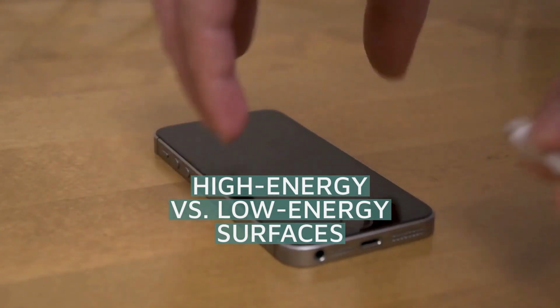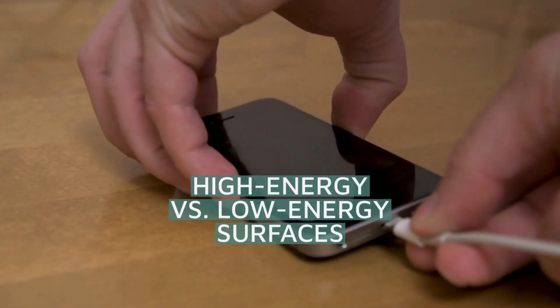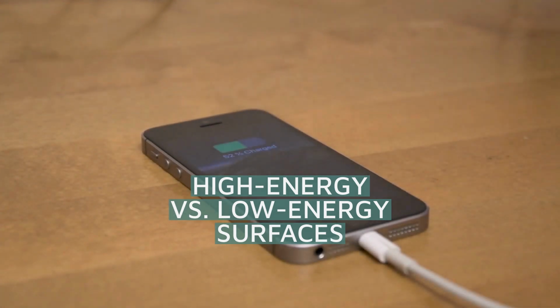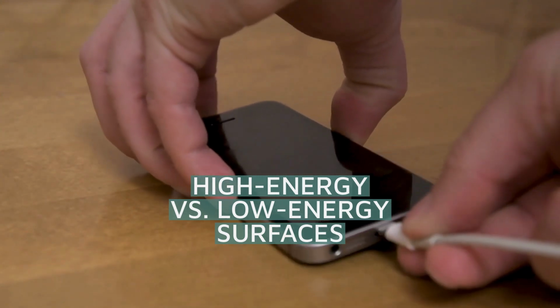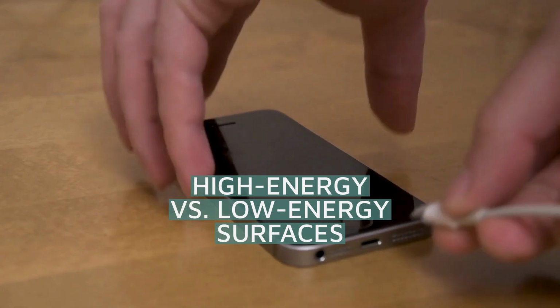Solids such as metals, glasses, and ceramics are known as hard solids because the chemical bonds that hold them together, e.g., covalent, ionic, or metallic, are very strong. Thus, it takes a large amount of energy to break these solids. Alternatively, a large amount of energy is required to cut the bulk and make two separate surfaces, so they are termed high energy. Most molecular liquids achieve complete wetting with high energy surfaces.